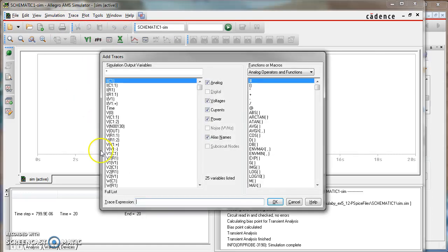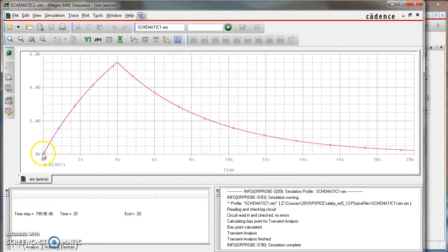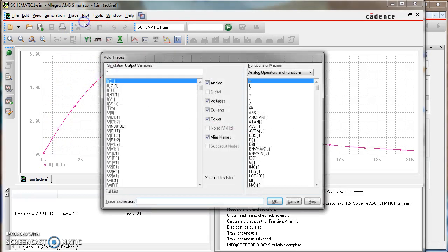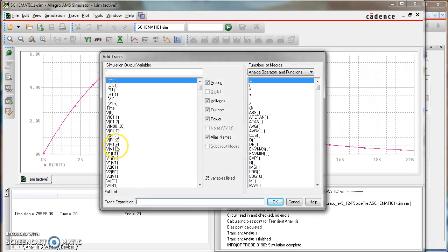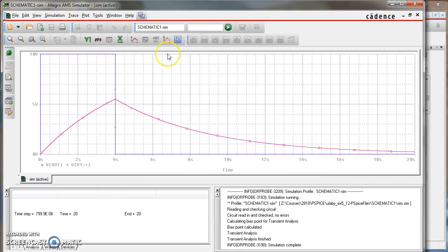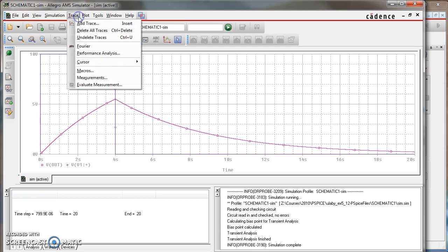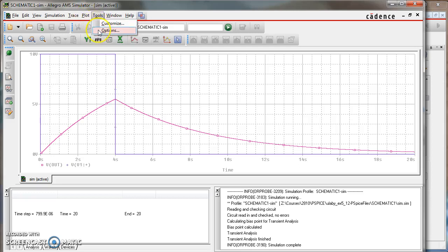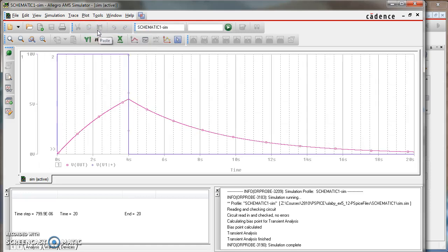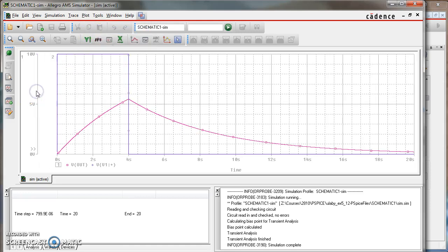Okay. So again, we can add and look at the voltage across the capacitor. And we can add voltage source. Now one other thing you could do, since the scale of the voltage and the current is so different, we can add a y-axis. Now we have 2 y-axes.